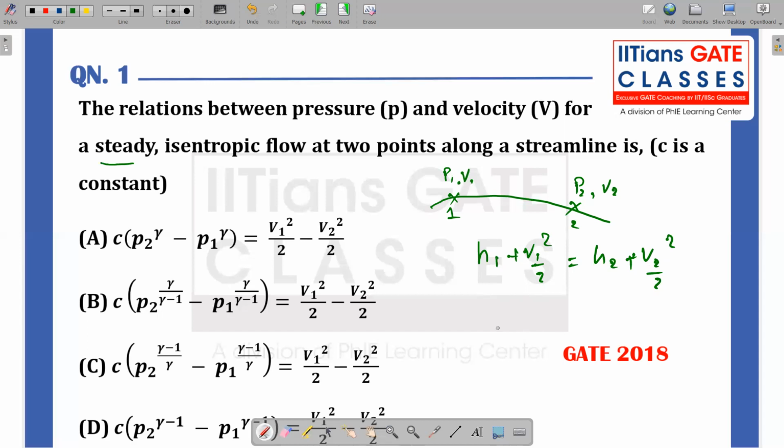So it's a general energy equation with no body forces and no viscosity effect. So this is an inviscid compressible energy equation in a steady flow, right? And if the flow is adiabatic, that has to be taken care of when we write this energy equation. Now I can write H is equal to CpT, if the gas is assumed to be calorically perfect. So I can write